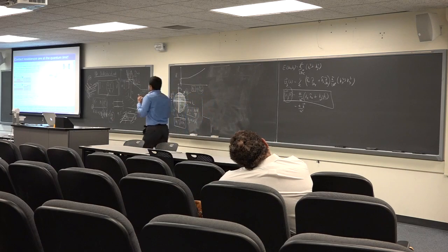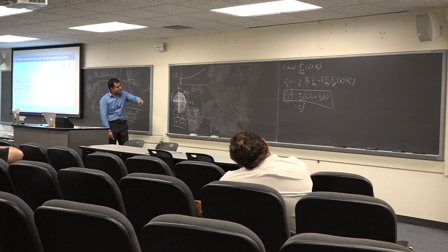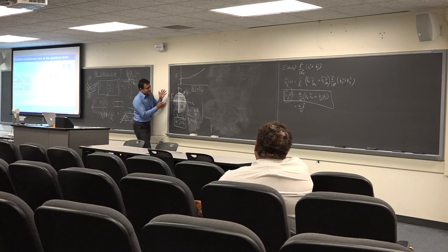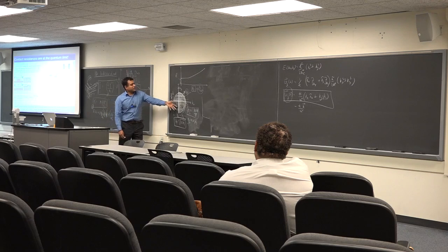Okay. So now we're going to calculate the current here, and you can see you can actually go in many directions. It's been a dream for many people for the last decade or so. Can I actually couple? The moment I make a left electrode, a source contact, I am coupled to these carriers because they are filling the right-going states, and the left electrode is filling these states. And now I'm going to calculate the current of these states.